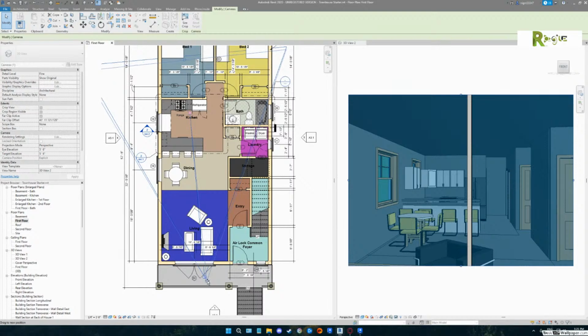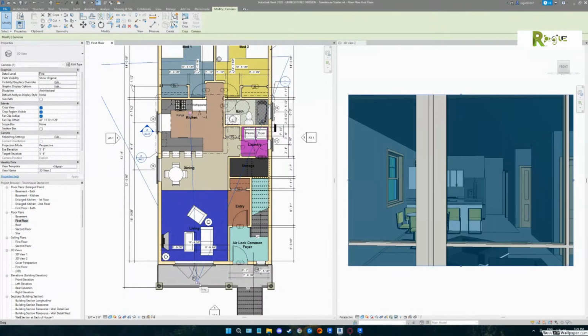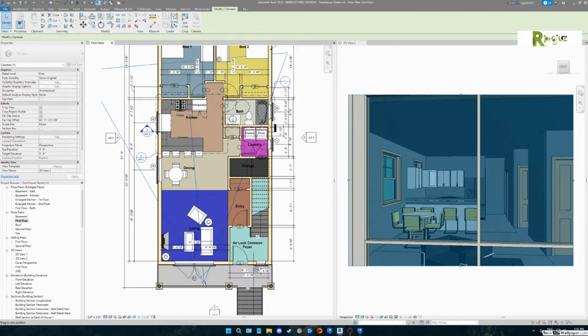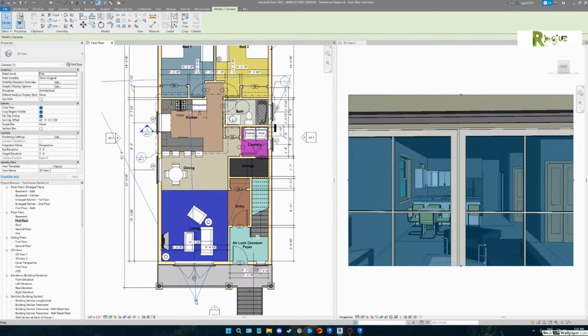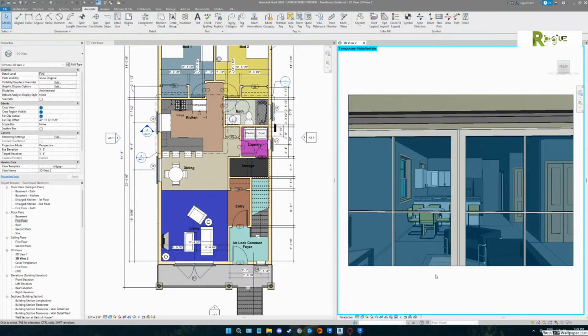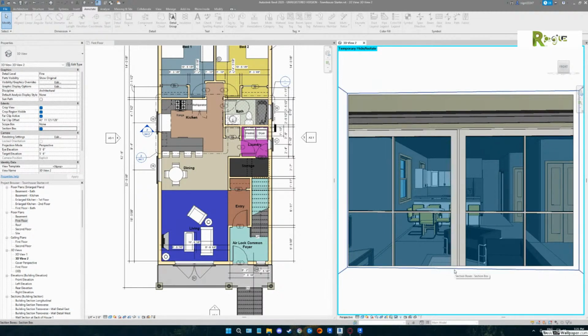That'd be good. See how you get so much more of the room when you're further out? Take yourself off the front porch. Perfect. Right there. I love that. Now, go to your 3D view. Okay. Turn your section box on. Hit escape two times so you're not picking on anything. Turn your section box on. See the section box? Yeah, pick that.